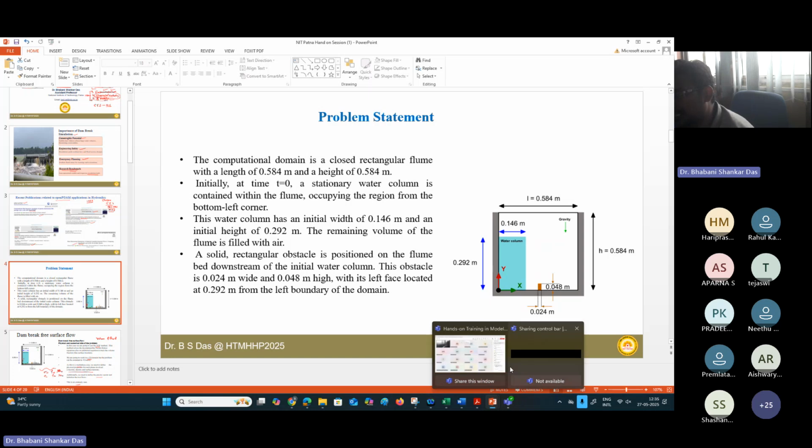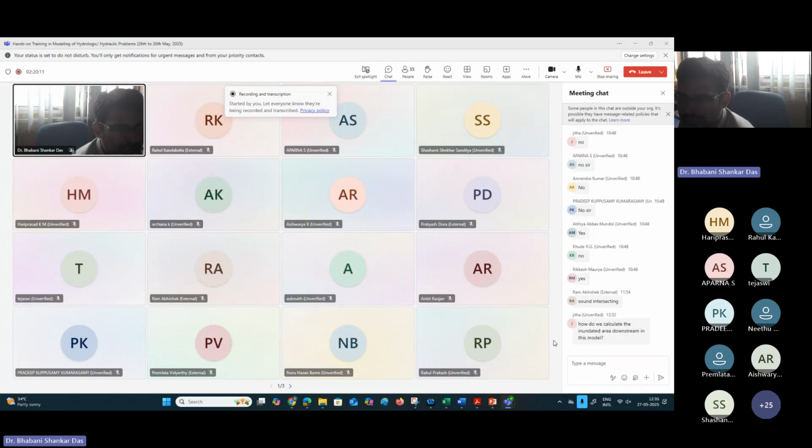The major thing in OpenFOAM is whether we are able to do the simulations perfectly, with those equations and those interfaces, those wave generations. Sometimes near the dam break at zero position, towards the downstream, at 10 kilometers, 15 kilometers, 20 kilometers, the magnitude of discharge will be reduced towards the downstream side. So the value of that magnitude in the beginning of the downstream. Those things can be handled by a 2D or 3D model more accurately as compared to the HEC-RAS model. HEC-RAS is also a good 1D model, but in OpenFOAM, you can see the velocity in the Y direction, what is happening in the Z direction, what the eddy formations are, and which type of structure can stand out in time of flood.